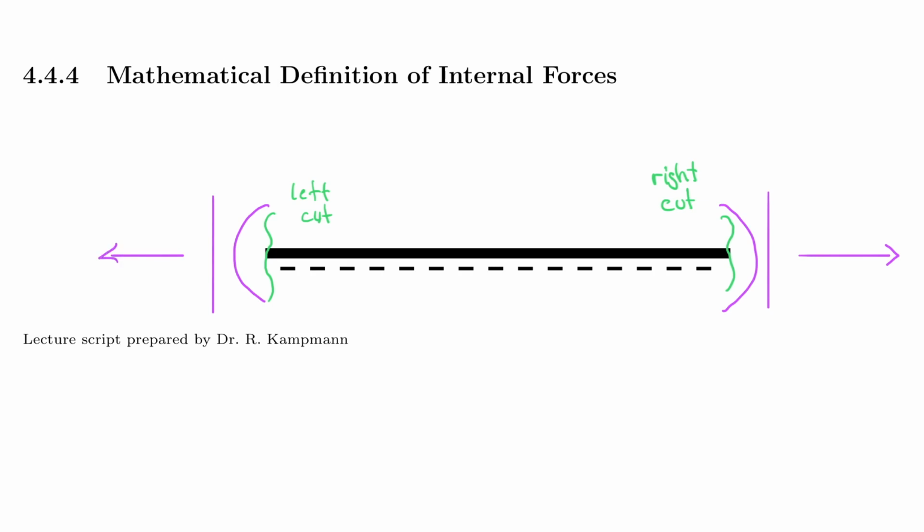On the left side, it's pointing in this direction. Then I have a shear force that goes in this direction and a moment that goes in that direction. And don't be confused, it's mostly similar to what I've done before, but now I want to be very clear why it is as it is mathematically defined. So here we have a positive V, here we have a positive N, and we have a positive M. And the same is true here, positive M, positive V, and positive N.